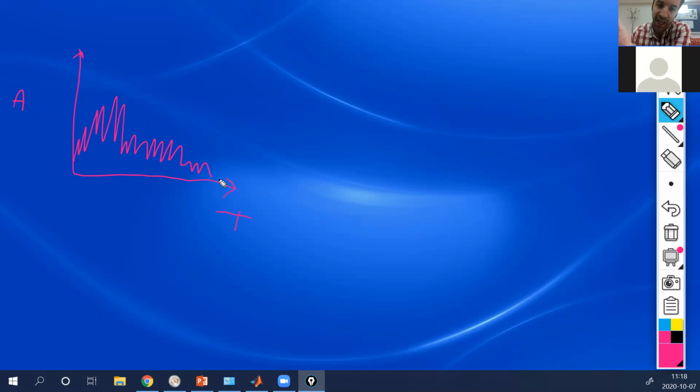But what people have done to create the design spectrum is that you compute the spectrum of all the largest earthquakes for a given region and plot them all in the same kind of graph, just on top of each other. Okay, and then you say, okay, the design spectrum here is going to be something like this.